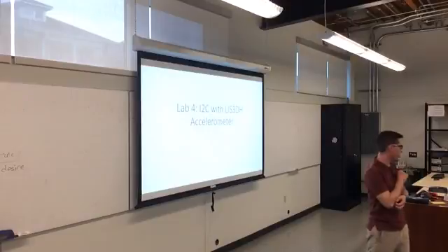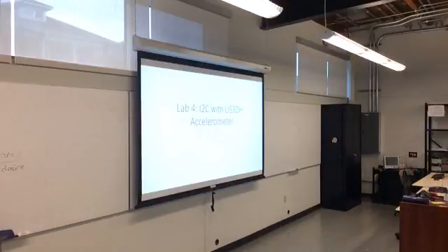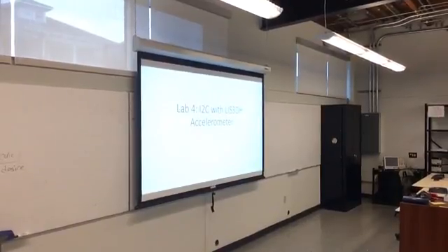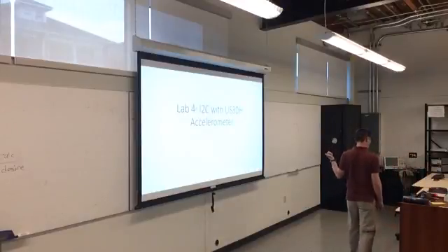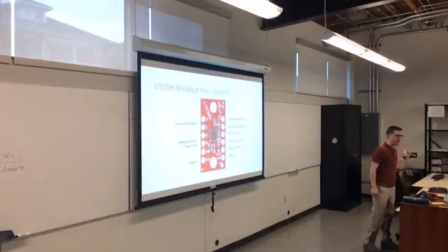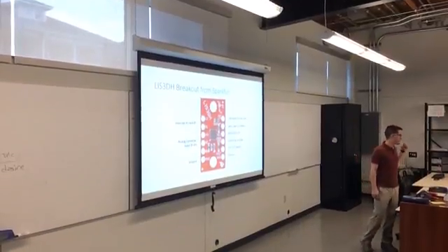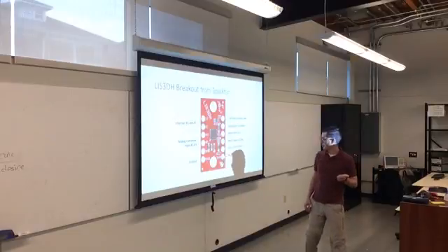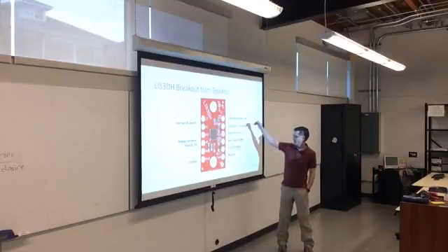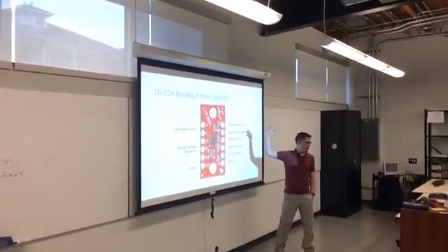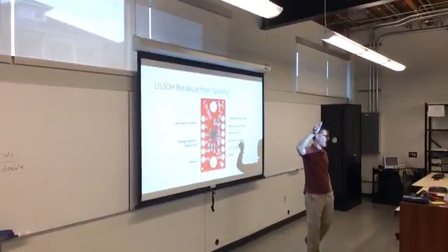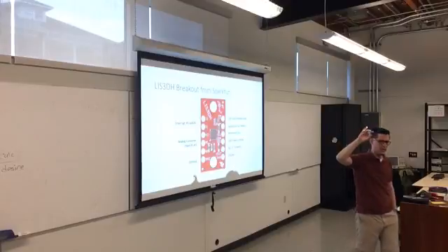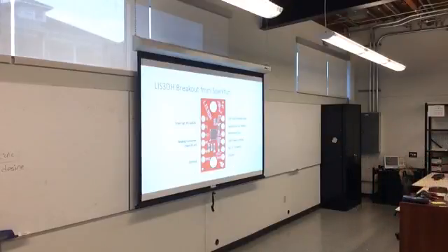Lab 4 is back to this guy, but you are going to use the I2C interface. So instead of connecting chip select, MISO, clock, data, all that, you're only going to actually connect up 2 lines. You're going to connect the clock line, and you're going to connect the data line. You'll always need power, and you'll always need ground. Here's the difference, though, is that you only need to make these 4 connections.